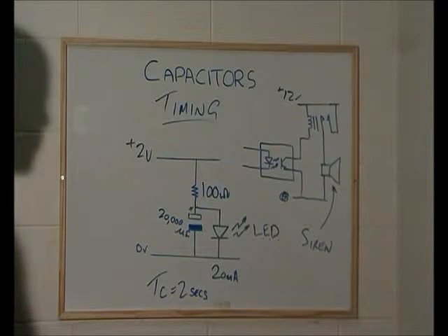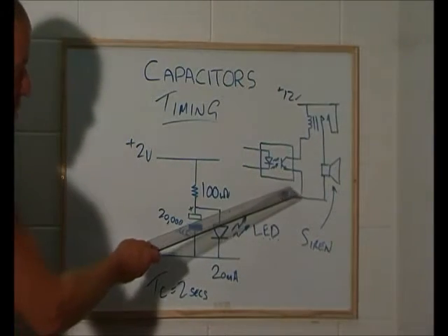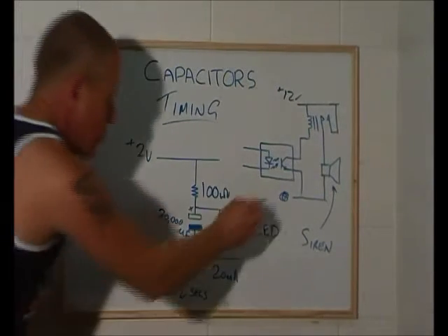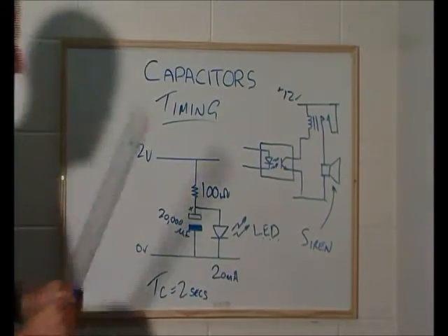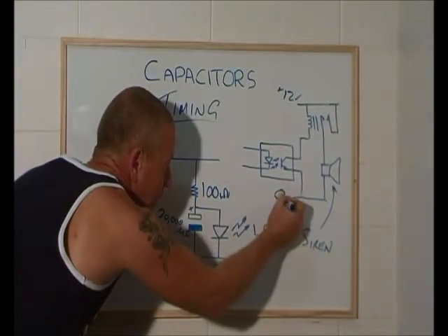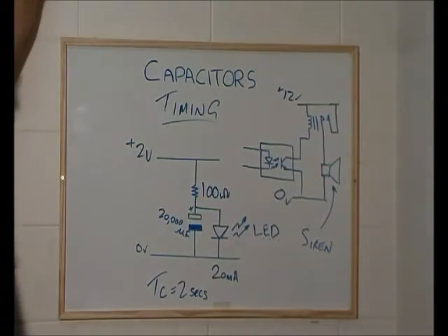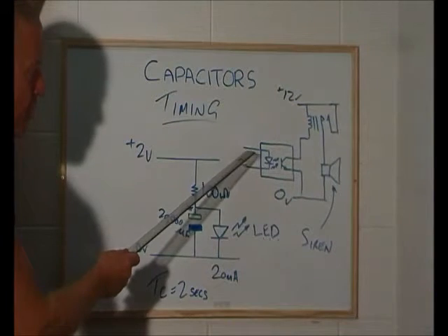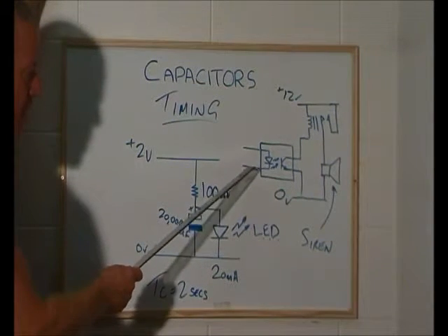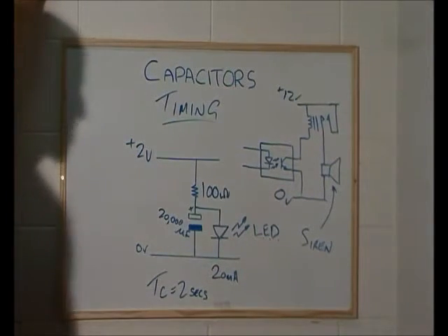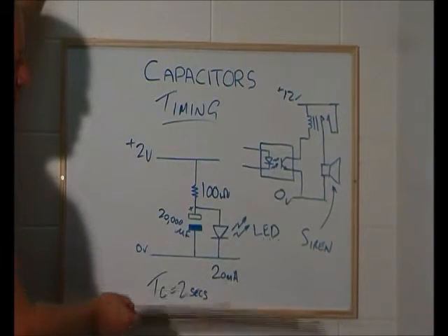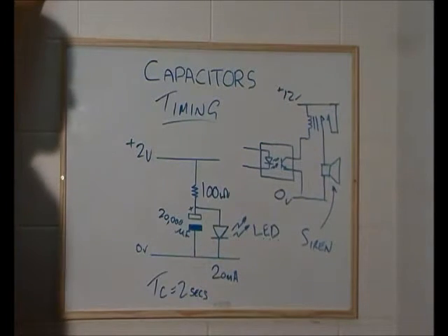Now, you may say, what good is that? Why do we want to just turn on an LED after 10 seconds? Over here we have what's called an optocoupler. Let me clean this up first. Get rid of that, it's been bothering me. Okay, that's better. Here we have an optocoupler. It's a 4-pin device, with 2 input pins, which are supplied to, you guessed it, an LED. And then we have a gap between the LED and what we call a phototransistor.